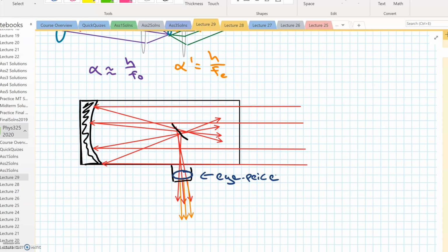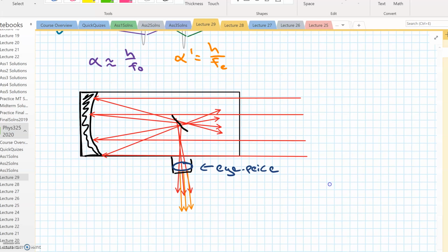You can kind of just rotate around a table. Randomness and the inability of the human hand to do something exactly the same every time tends to average out in such a way that you grind out naturally a spheroid out of the mirror. And then what you do is you put a small correction to the center of the mirror to make it a paraboloid. There are other ways of getting around this.